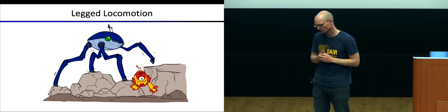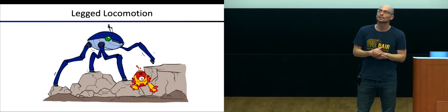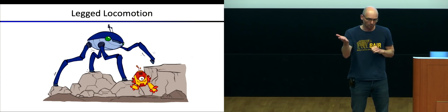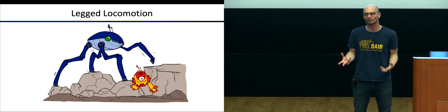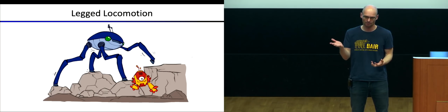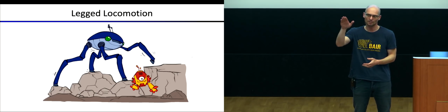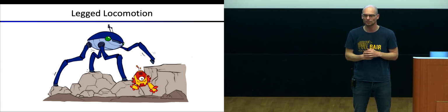Maybe a question related to that is, how much power does this thing actually have? This helicopter had, in inverted flight, where it has more power, 3 Gs. So we could generate 3 times the force of gravity. Of course, you need to generate one of them to even stay up in the air, but you still have 2 Gs left to do other things with. And regular flight had about 2.5 Gs maximum acceleration.